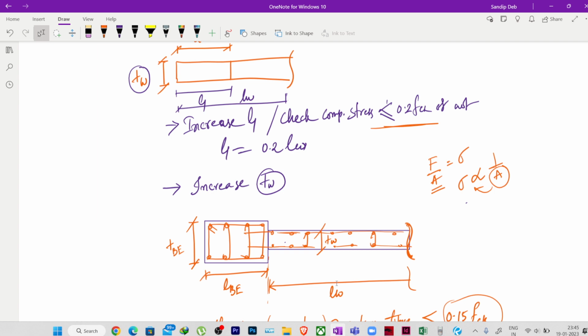Okay, so in high-rise structures, for some of the walls where the concentration of the lateral forces will be higher, they provide some shear walls, and they also provide some RCC partition walls. So along with the shear walls, those RCC plain concrete walls also provide some lateral stiffness to the structure, right? And the rest of the walls they make by normal brick. Okay, that is also seen. So both are there, the combination of shear wall and plain concrete wall.